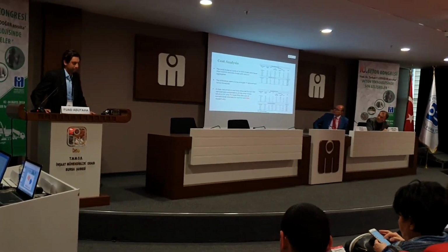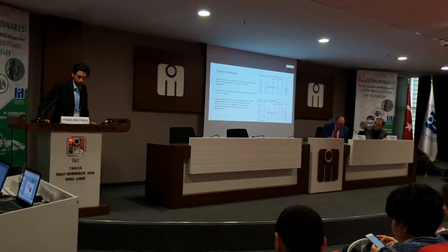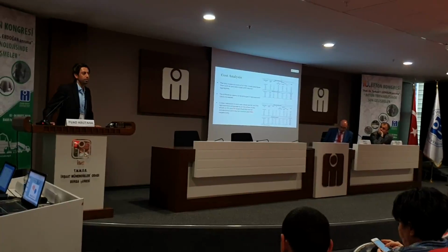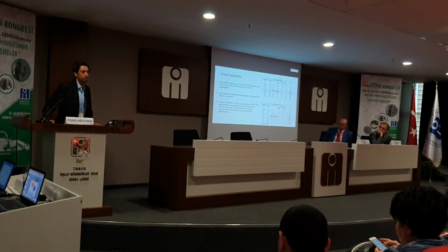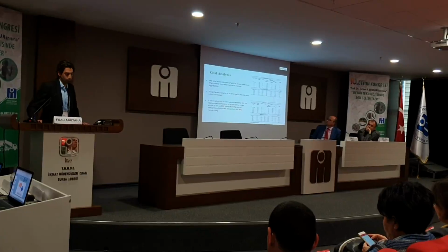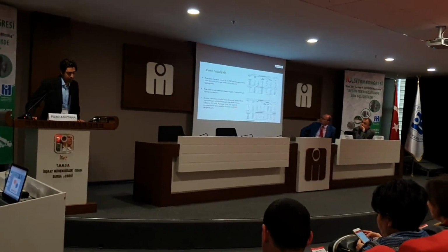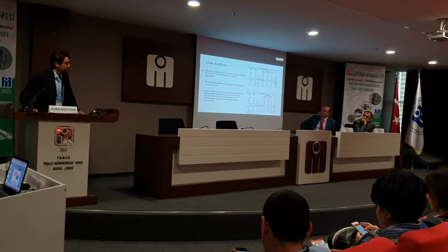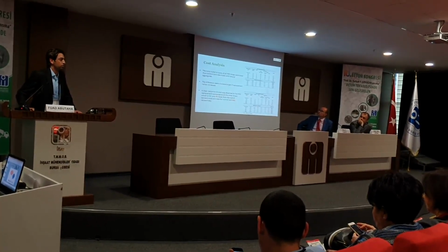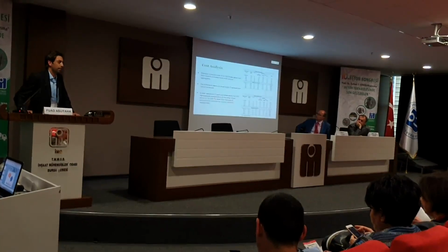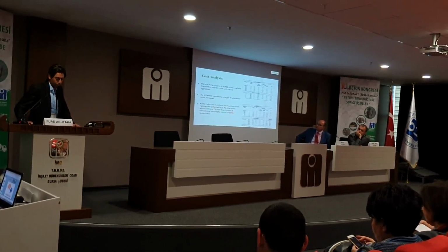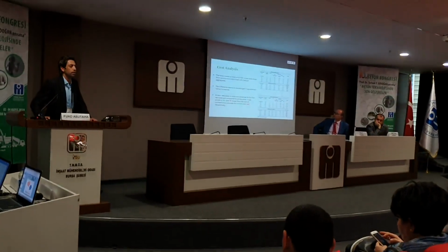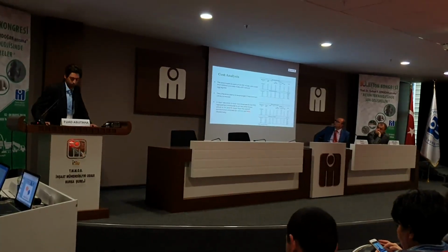So for the cost analysis, the total material cost for all POC mixes was lower than the control mix. POC is cheaper than natural aggregate, and the higher the percentage of use, the cheaper it is. It was 18% cheaper than the control natural aggregate concrete for normal concrete production, and 7% lower than the control for high strength concrete.